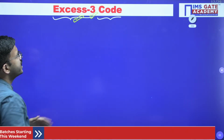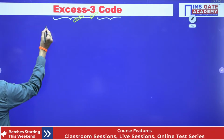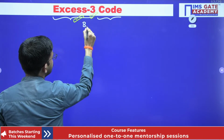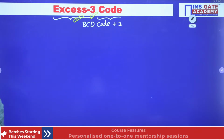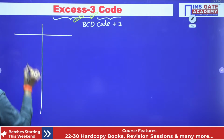Whatever the BCD code we got, that BCD code you have to add 3, so that whatever the corresponding code you are going to get, that is nothing but XS3 code. So XS3 code is nothing but BCD code plus 3.